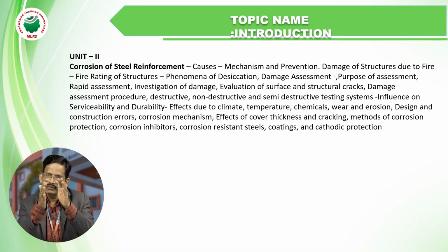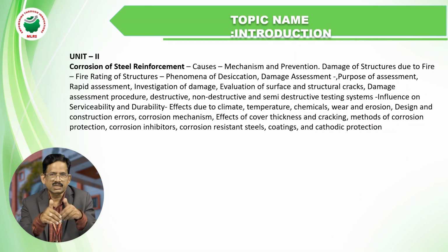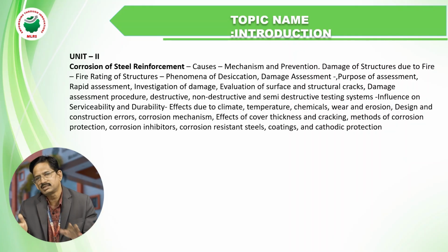The concrete is very strong in compression and very weak in tension. The steel is very strong in tension. That's why we provide the steel in concrete structures. So, both the concrete and steel together take the compressive stresses as well as the tensile stresses.